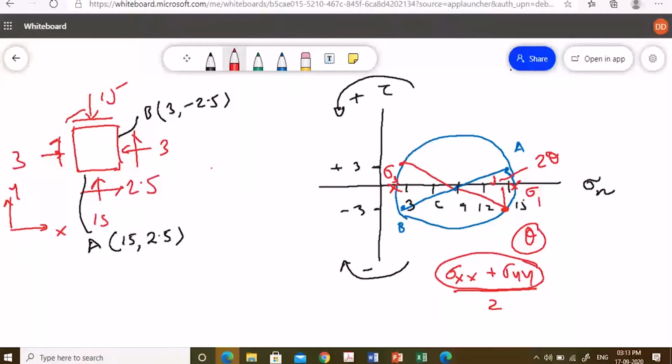So in a Mohr circle, the center is one of the invariants of the stress. So it doesn't matter which plane you take. Every point is a plane, right? Because here all points are planes. So it doesn't matter which point you take, the center doesn't change. That's why it's invariant. Now what is the other one?